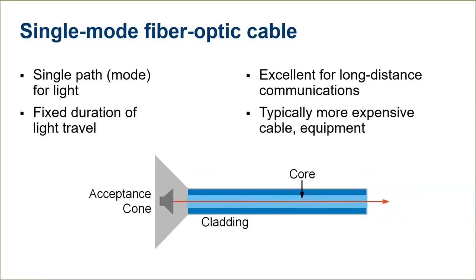Now, single mode fibers have an extremely small core that is less than 10 times the wavelength of the transmitted light. At this level, the light propagation can no longer be analyzed by geometric optics like Snell's law. Instead, it follows the differential equations of Maxwell's equations of electromagnetism.